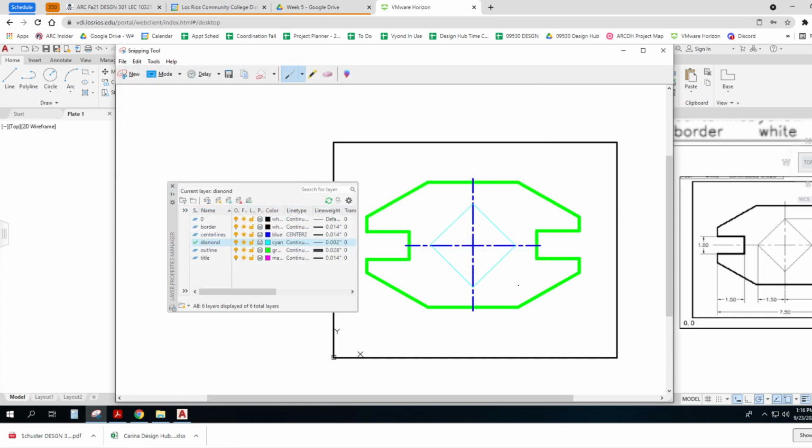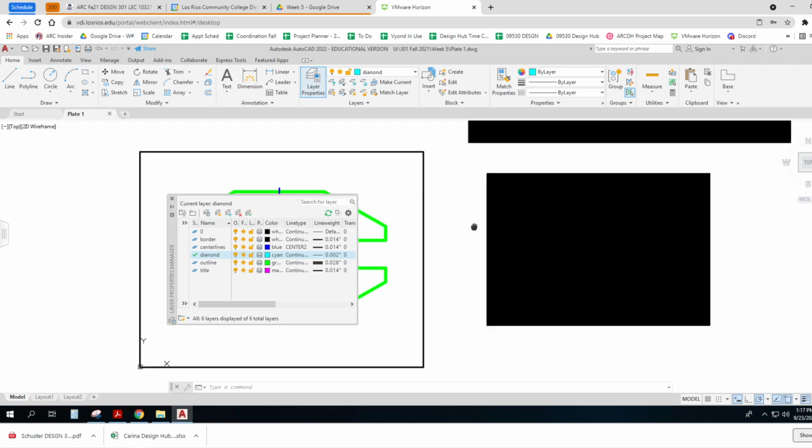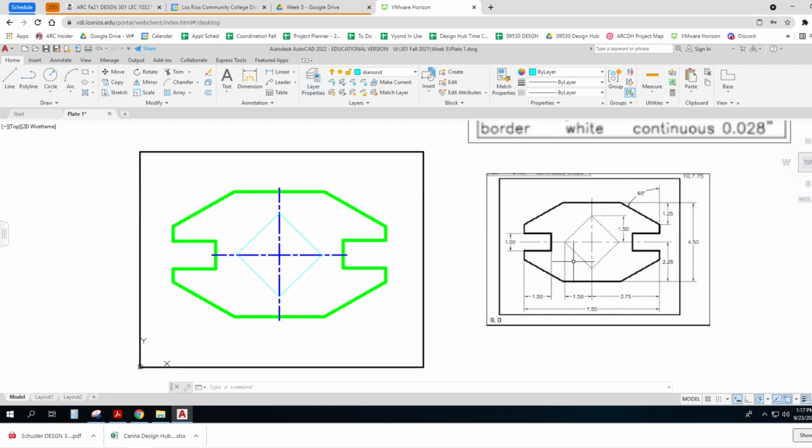So we just go over these steps over and over and over again until you get good at it. So that one included the chamfer command, some offset commands, some O snaps, some trim. But I mostly used exactly the information that was given to me. That's how I tend to try to draw. Okay, it said it was down 1.25 at 60 degrees. So whether you use the chamfer command or the draw and trim and mirror won't really matter.